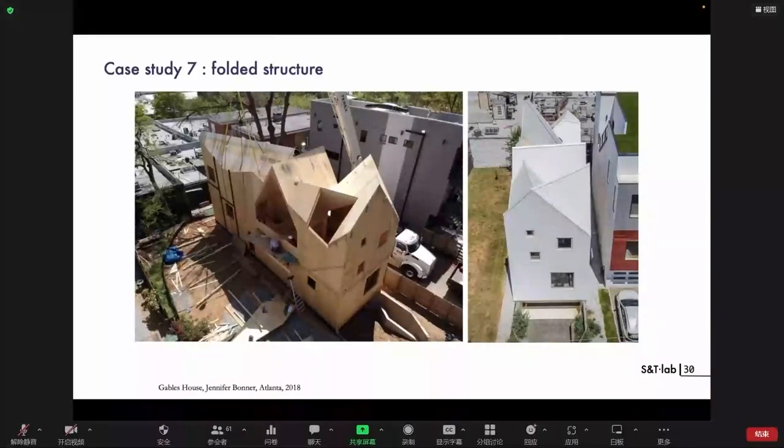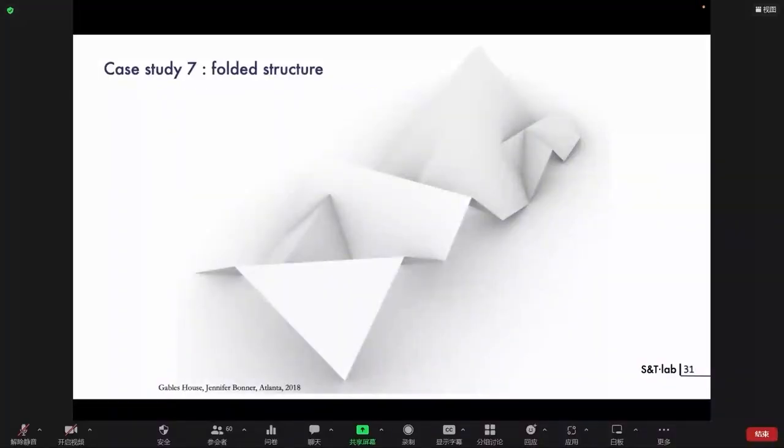And this principle of six combined gable roofs enables the architect to offer something like a free plan because of the span, but at the same time very specific sub-spaces because of the roof that will stay visible from inside. So this is quite a monolithic roof, which we can see as a folded structure.